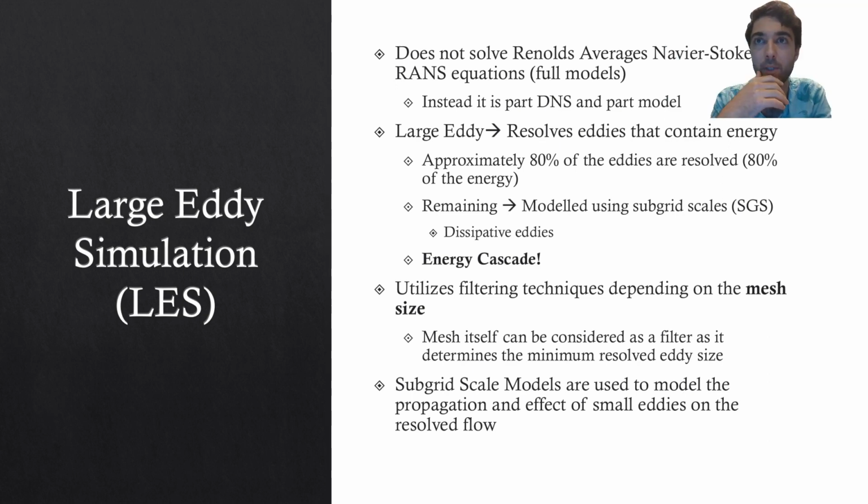So depending on your mesh size, the amount that will be resolved will change. If you have a fine mesh, you will be solving pretty much everything. If you have a coarse mesh, you will be solving less than the fine mesh. So large eddy simulation is very sensitive to your mesh size, the cell sizes, and whatnot.